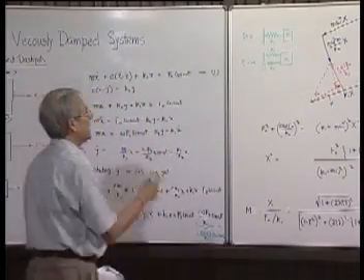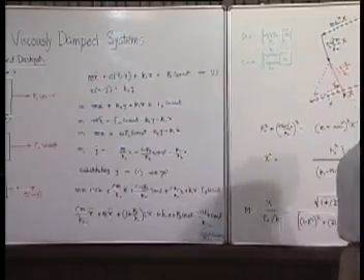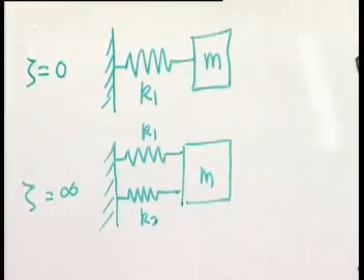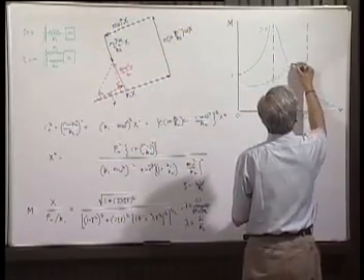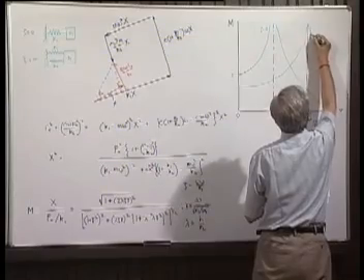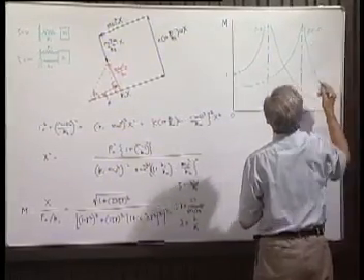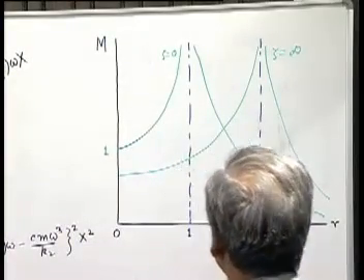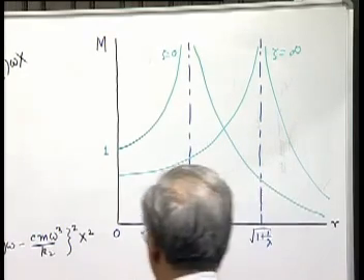And obviously the natural frequency and that ratio will be then 1 plus this. So for this, it will again behave like a simple undamped case, and the frequency response or the magnification factor diagram will look like this.